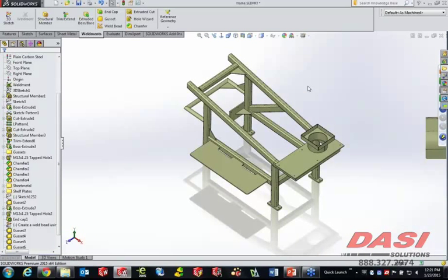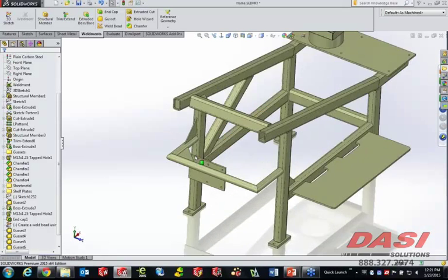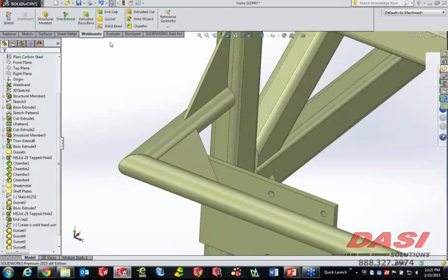Now, those types of use cases for gussets were also challenges for our weld tool. The weld tool started changing in a very, very positive way back around SOLIDWORKS 2010, where we switched from the fillet weld to the weld bead function. And the weld bead is more of a virtual weld. Virtual meaning it doesn't physically create solid geometry, but you do get feedback for the length of weld, potentially the weight and cost of that weld, and then the auto weld symbols for those as well.